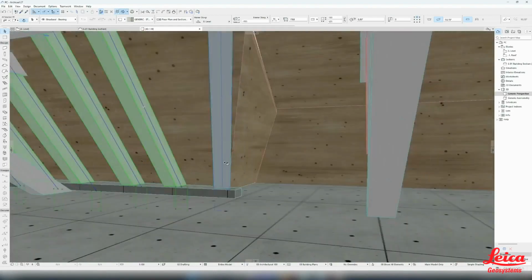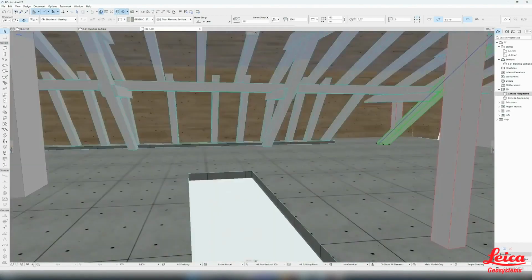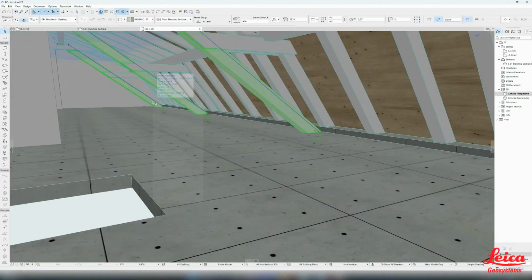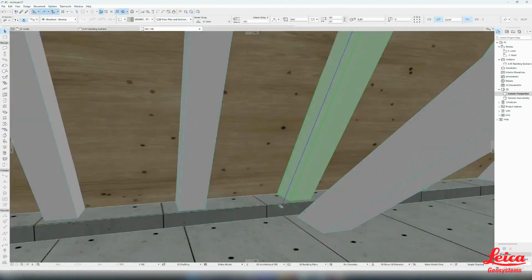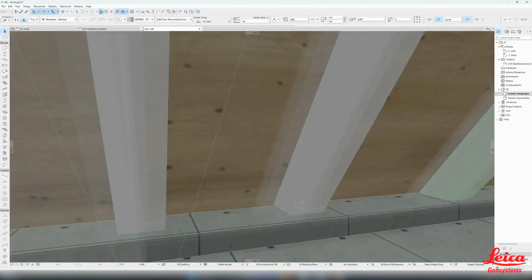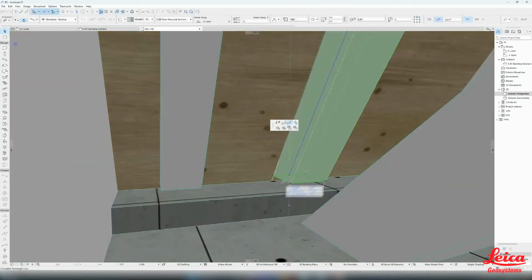After that, select the roof, which should trim the previously selected elements, and click Add as Operator. Then select the desired operation in Choose Operation and press Execute. This tool can be used to cut and clean all elements.